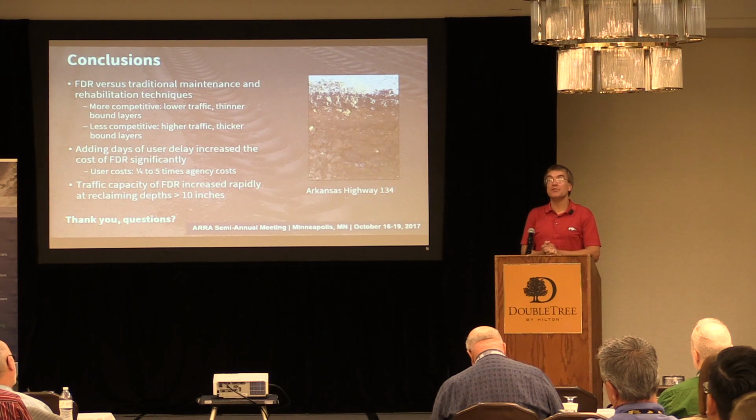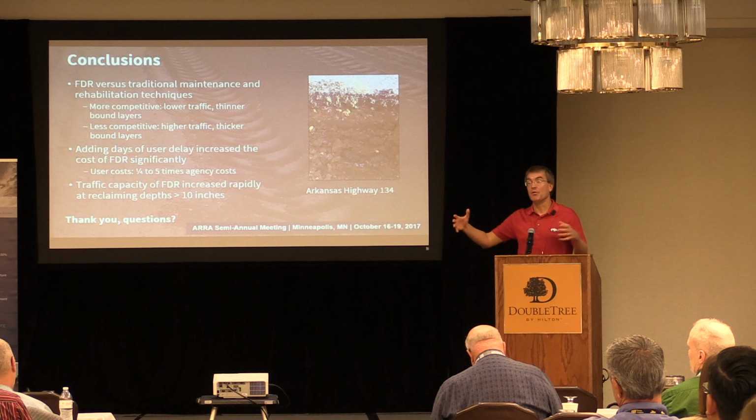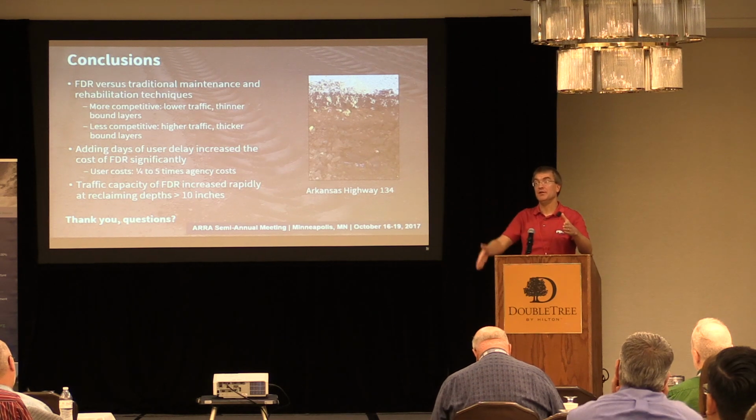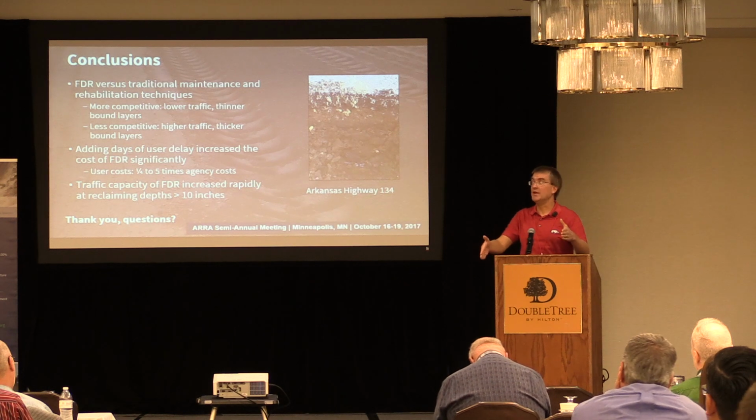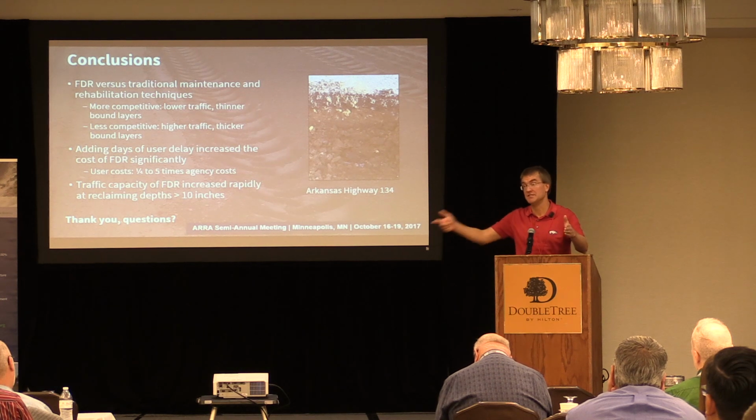So for the remove and replace analysis, we assumed that every 11 years we would put an overlay on top. That was the maintenance strategy. We wouldn't remove it and replace it every year. It's just that after 11 years we would put, oh, I can't remember if it was a 2-inch overlay or a mill and fill, but it was the 11-year cycle of maintenance. It wouldn't be a chip seal every 6 years. It'd be a mill and fill every 11 years, yeah.